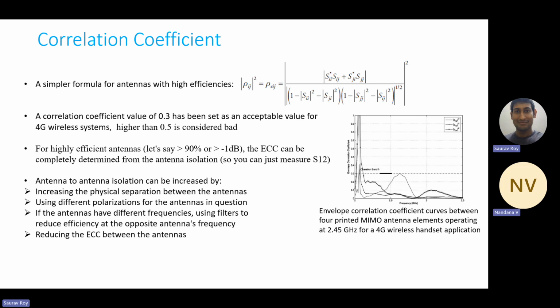Generally, this is a topic of active research. People still work on these topics. If you have a MIMO antenna, generally people work with small patch antennas. Let's say on the same substrate you have 4 patch antennas, so it can work like a 2x2 MIMO array. They will have 4 different ports. So how to design it so that these 4 antennas have less correlation and more isolation? This is also a topic of research nowadays.